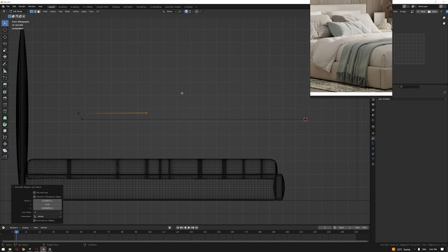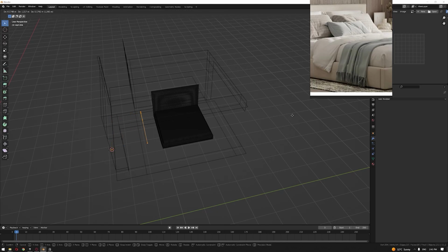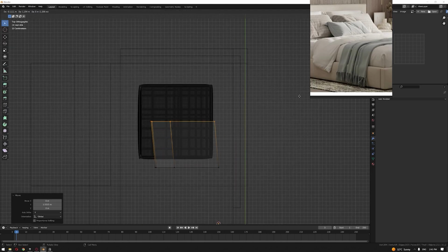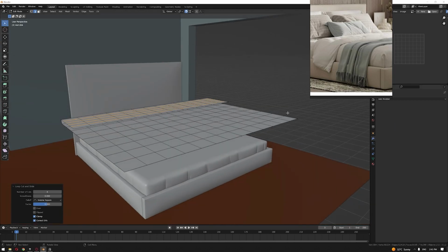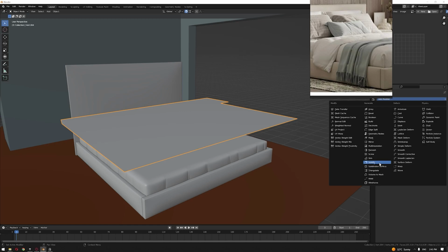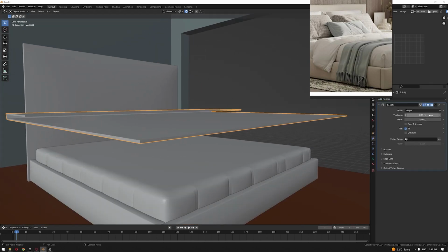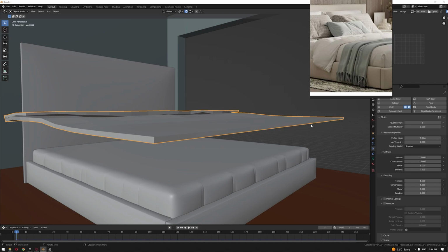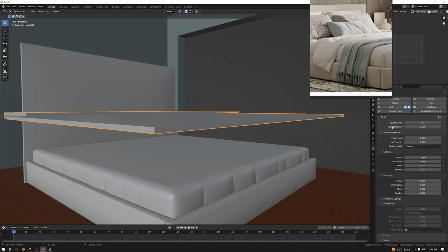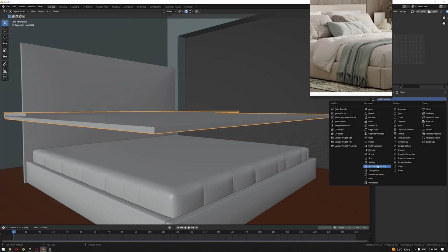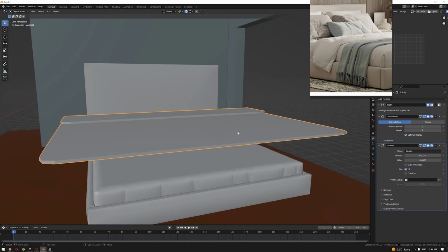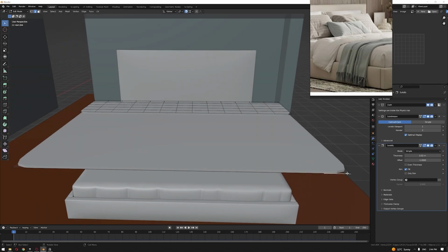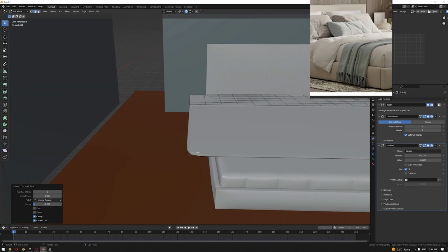Create the same shape. And now if we move to the top view, we'll apply a thickness to this object by adding a solidify modifier with a thickness of 2, for example. And then we will add the cloth properties. Make sure you're on frame 0 or 1, and apply a subdivision surface to that as well. I'm going to keep the solidify under all of them just to see how the result is coming up, and add edges at the end as we did with the bed base.